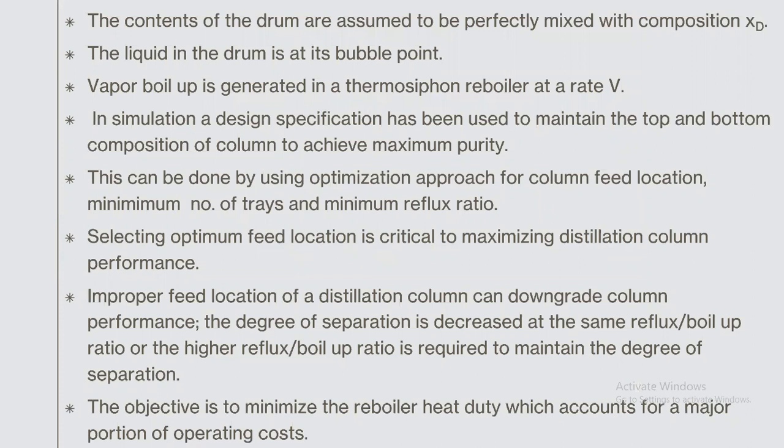So the contents of the drum are assumed to be perfectly mixed with the composition XD. The liquid in the drum is at its bubble point. Vapor boil up is generated in a thermosiphon reboiler at a rate V. In simulation, a design specification has been used to maintain the top and bottom composition of the column to achieve maximum purity.